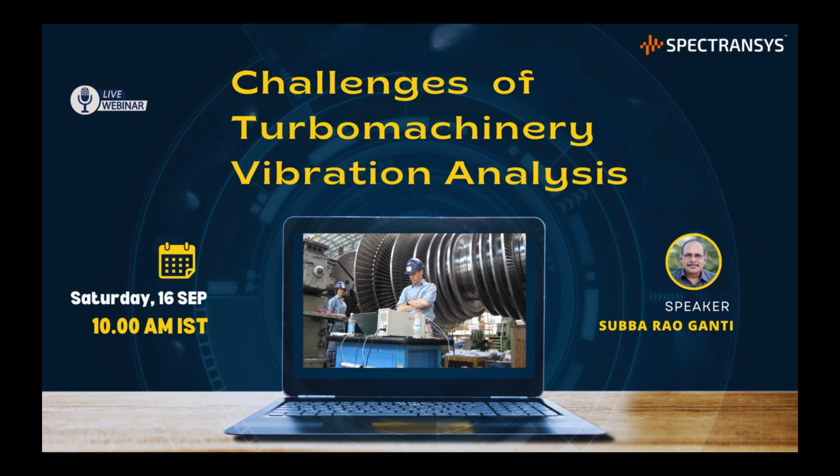See, actually, if you look at the oil and gas environment, that's where there is a lot of streamlined documentation. API standards, as I told you, American Petroleum Institute standards. For example, if you are buying a steam turbine or a gas turbine for refinery applications, or a gearbox or a centrifugal compressor, there are certain API standards, API 612, API 614, 616, 617, like that. They give you a lot of rotor dynamic information in those standards. So for those applications, you can go through this.